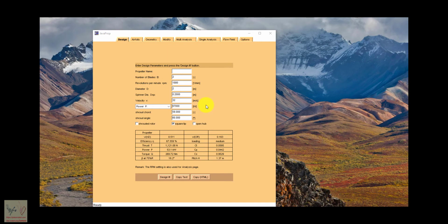With respect to propeller design, these are all parameters that come from the way that this drone works. It seems like when you add more blades, you don't really get more thrust. What happens is the total thrust of the propeller is divided among the blades, so you have less thrust pressure on each blade, but the propeller weighs more.